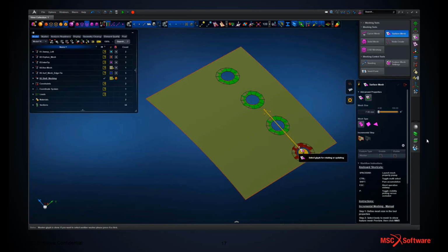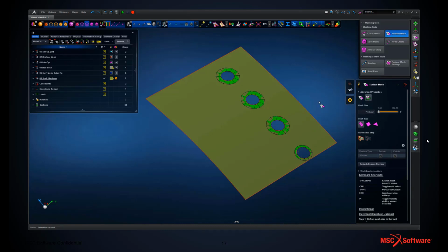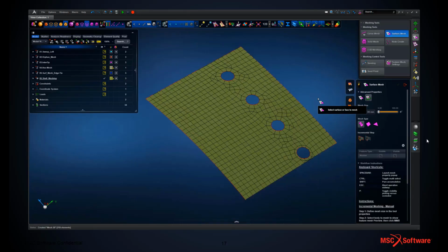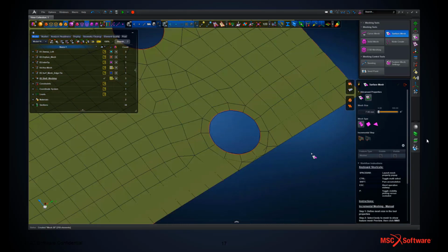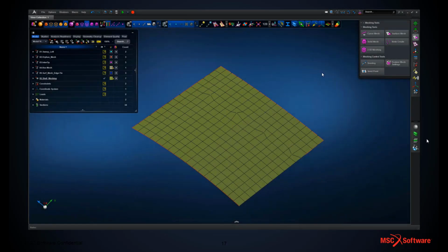Here it's found the hole, it's shown it in red, it says we can't fit that washer in, so we can change the washer width, just decreasing that for that single region and then remeshing the whole structure, and those features are preserved within the full mesh definition. We've got the ring of elements as required.